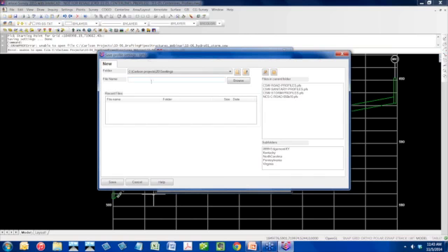Now, this may be a company standard. I always kind of point out to people, if you have a profile that you draw in for existing sewer, and you have it also draw proposed sewer, you may have different layers. So you may need to create multiple PFS files, one if you're doing existing, one if you're doing proposed, and things like that. You can see that by default it's put it in my settings folder, and you can see there's already some here.